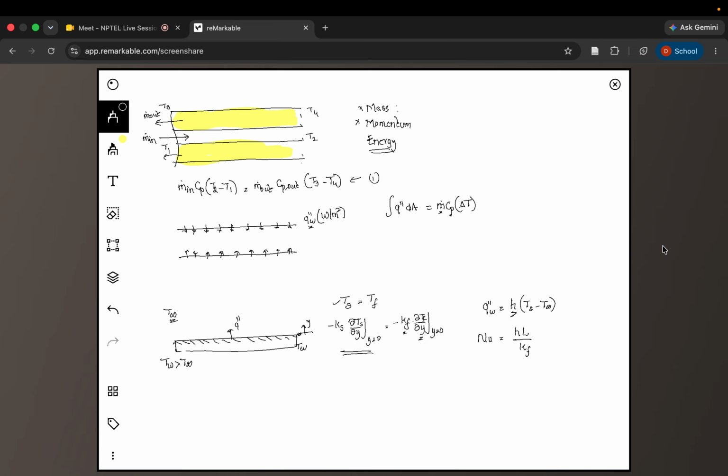Again, just to keep a note, whenever you are talking about solid, fluid, etc., just understand this is a property of the flow that is happening. Convection is happening inside the fluid, so all these have to be with respect to the fluid. Since h is a function of different quantities, Nusselt number will also be a function of fluid, flow properties, geometry, etc. For every particular geometry, as we go through the course, we will derive different correlations, different relations for this Nusselt number. And this Nusselt number is going to depend on, as I said, the fluid flow geometry.